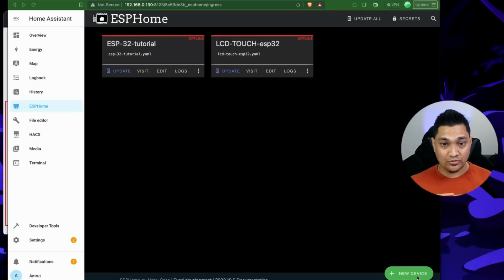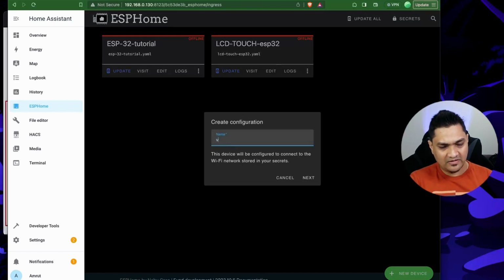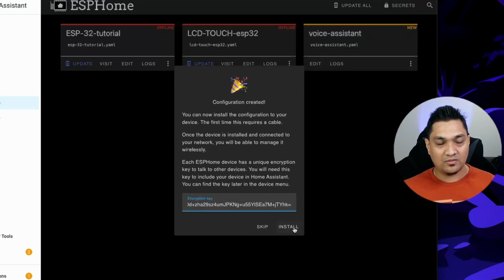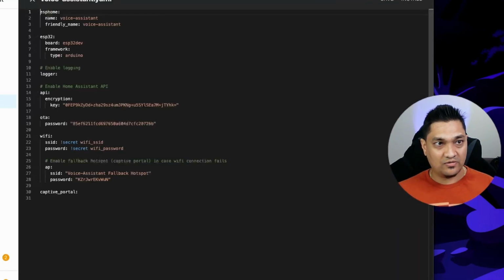The first thing we're going to do is create a new device here. I'm going to click on continue, and let's give it a name like voice assistant. I'm going to click on next, and here I'm going to select ESP32 because I have an ESP32 dev board. So let me select that. Now I'm going to skip this because I need to put in some code here. This initial code that you have, I'm going to keep as is, but I'm going to add my code that I will need to actually create my voice assistant. So let me copy and paste this here.